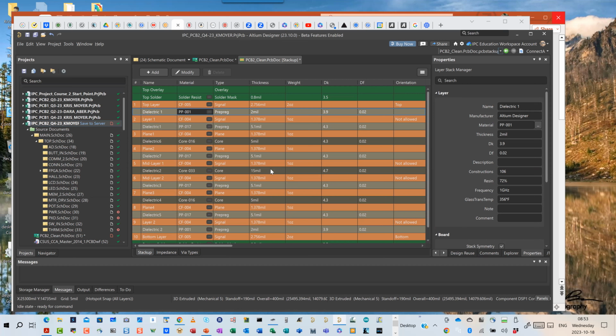With one caveat here, and we talked about this in course 1, and we'll talk about it again in manufacturing. This idea of foil versus cap construction. By far, from a manufacturing point of view, it's always best to have the outermost layer be the prepreg layer, so you've got a sheet of foil. If you make the outermost layer a core, it means that outer core has to go through the etch processing twice, once for the underside and once for the outer side during the plating process.